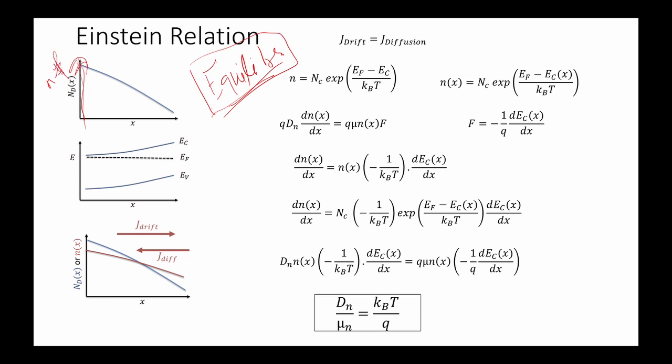So this is the concentration of holes and concentration of electrons, which is varying in the direction x. Okay, so how this band diagram will look: because we are in equilibrium, there is no flow of current. If there is no flow of current, the Fermi level will be constant. There won't be any gradient in the Fermi level.